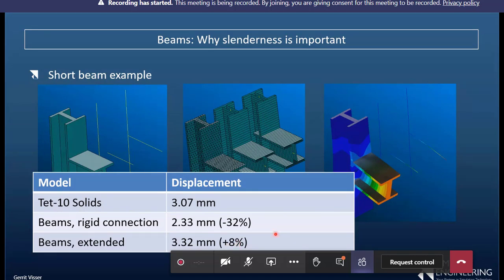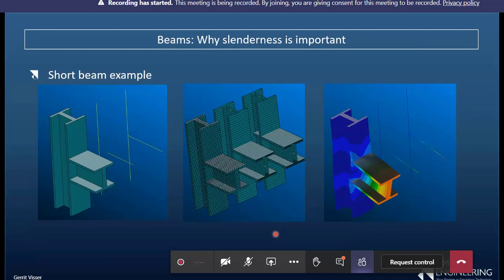Now let's just go back a little bit and see why this one would deform. Well, no, let's first try this one. Why would this one deform more than this one does? Because I've got a rigid connection there from there to there, which is supposedly that attachment, and that's exactly the issue. If I look at the deformed shape at the back, I'll see the slight S, but if I look at the front, I see a significantly more exaggerated deformed S shape.